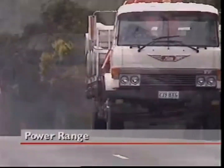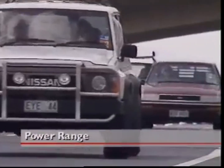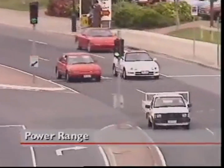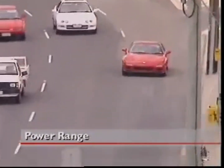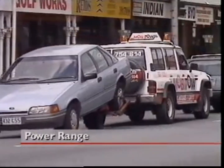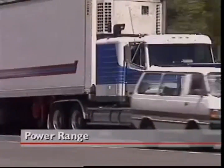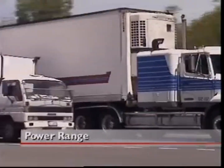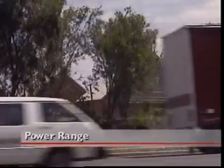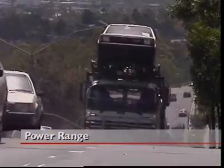An engine that is quite powerful may not be designed to produce its maximum power over long periods. A petrol engine in a car may give good acceleration in short bursts, but it can overheat or fail if it's operated at maximum speed and power for too long. A heavy-duty diesel engine in a large truck is designed to operate near or at its maximum speed and load for long periods without damage. Many diesels will suffer if they are run on light loads or at low speeds for too long.